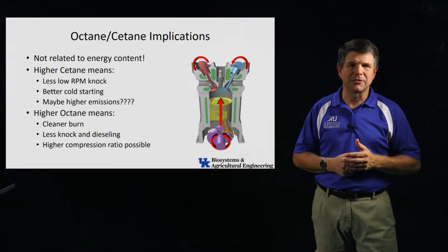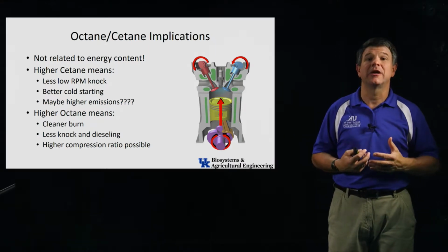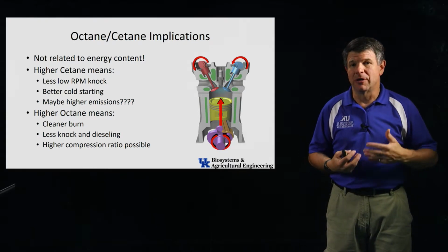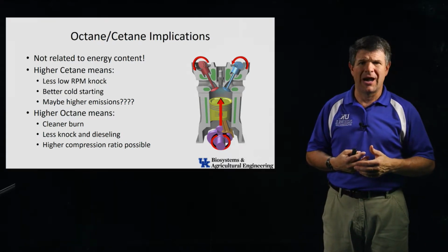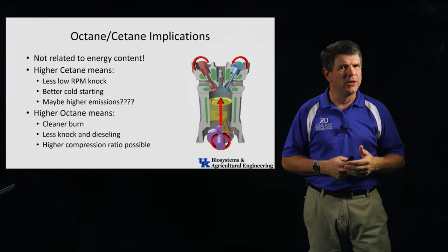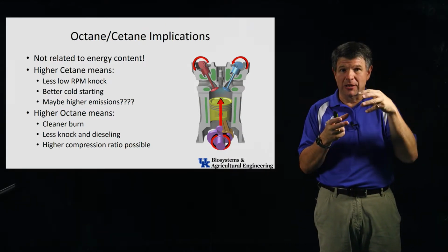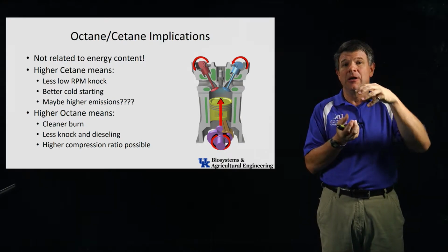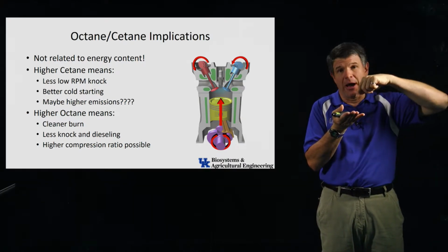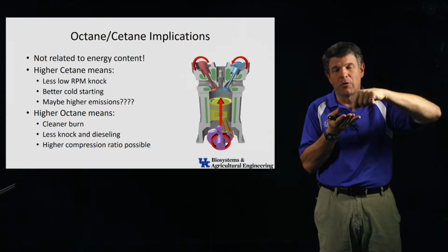All right, but here's the weird thing about that. We think, hey, I'm going to spend extra money for high cetane fuel so that it burns better, but I might get higher emissions, really? So what can happen? The critical thing is that when I inject that fuel into the space at the top of the cylinder, I want to be able to get the air and the fuel mixed together.